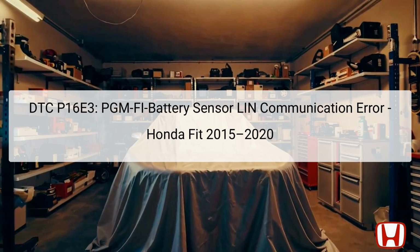DTC P16E3 refers to a specific diagnostic trouble code indicating a LIN (Local Interconnect Network) communication error concerning the battery sensor in the powertrain control module, or PGM-FI (Programmed Fuel Injection) system. This error can impact the vehicle's performance, as the battery sensor plays a crucial role in monitoring the battery status and communicating vital information to the PCM.